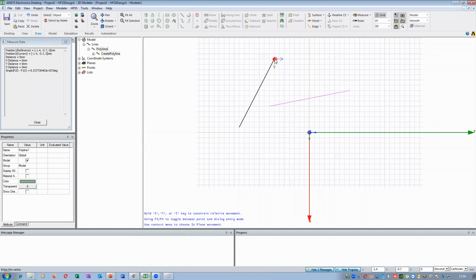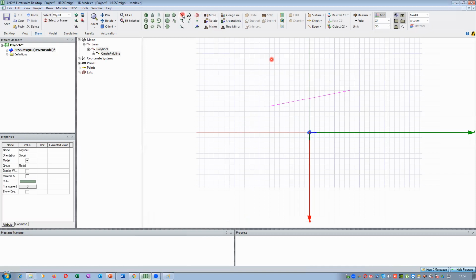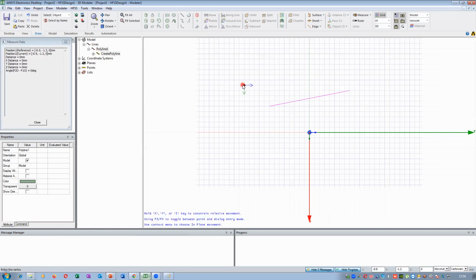Again, it will show two arrows. So doing it again. So first click on one point, then you will see two arrow marks, which is along the x-axis and which is parallel to the y-axis. That means you can navigate in both the axis, that is x-axis as well as y-axis. Otherwise, you can move in that plane. That is the point. So now I will click the second point of the line, then again it will show the axis representation, the navigation tools. So if you want to continue like this,